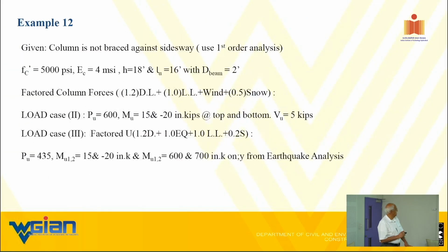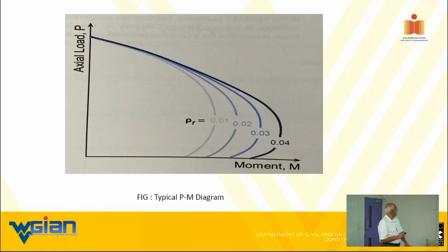Sorry, I'm going in the wrong direction. That is the zero moment. That is Pn max, which is a very simple thing to compute here, since we don't even have to worry about the area of GFRP in compression, so it's just a one-step deal to establish that point. Then it gets complicated to sweep through this curve.